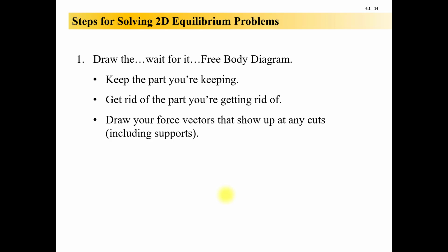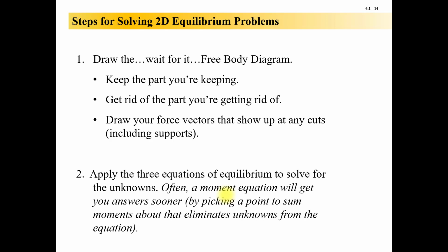And at any cut surfaces or any cuts that you make when you draw your free body, that's where your force vectors show up. Then, after you've drawn your proper free body diagram, you apply your 3 equations of equilibrium to solve for the unknowns. And you often sit back and say, where should I start? A moment equation will often get you there fastest.